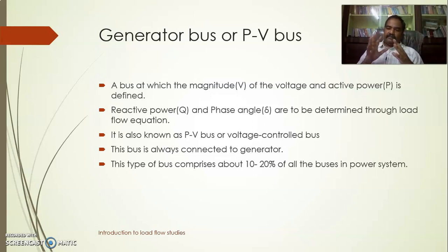Now I have a 100 bus power system, and I have 20 generators which are catering to, let us suppose, 80 load buses. Now if the generation, the positive power injections of these 20 generators, is equal to the negative power injections of these load buses, this is the demand and this is the generation. Now generation is equal to demand, but nobody has considered the losses. So where do the losses come from?